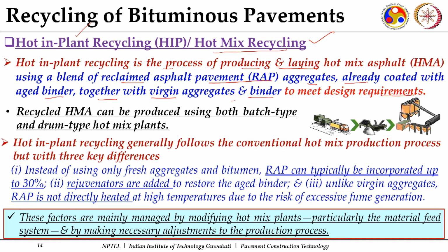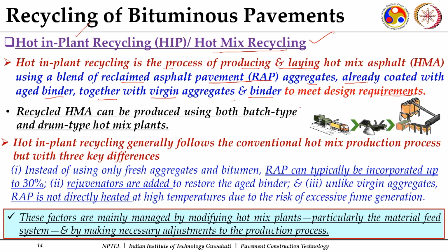Design requirements may be in terms of air voids, or in terms of stability, and they are the same, because we are going to use it as a base course, binder course, or wearing course. Whatever requirements are there for your virgin mixes, the same will be there for your recycled mixes also. This recycled mix can be produced using both batch type and drum type hot mix asphalt plants.